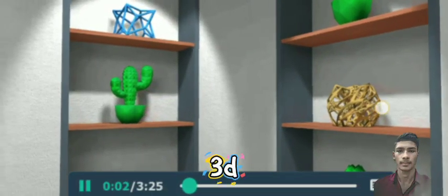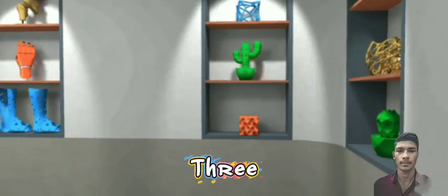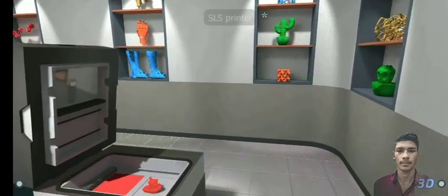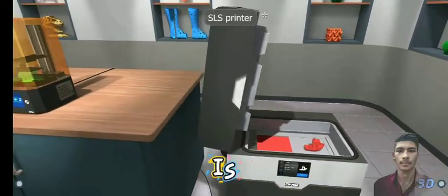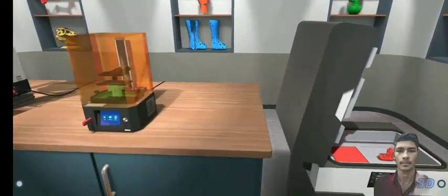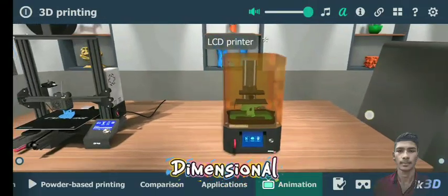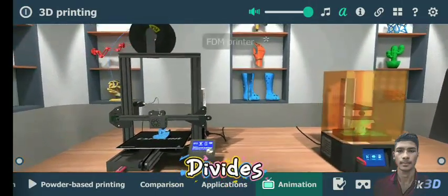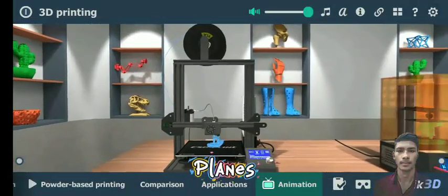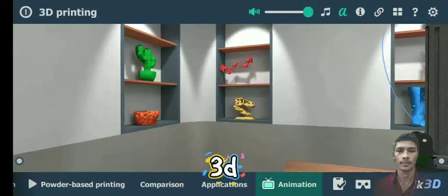The term 3D printing refers to a number of different technologies with which three-dimensional items can be made. The basic principle is the same for each method. The item is printed layer by layer. As a first step, a computer program creates a three-dimensional model of the object. Then, another program divides the model into section planes and, based on these, sends the list of instructions to the 3D printer.